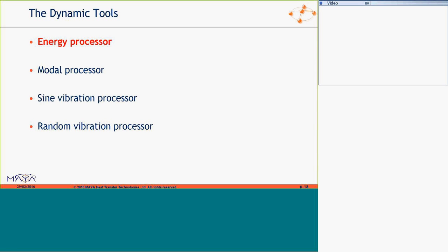So what's important is to understand your modal basis, because you'd be specifically exciting some modes and perhaps not others. Do your modes form a valid basis in terms of effective mass? Do we have enough rigid body mass included in all the modes here, or do we have modal truncation effects?